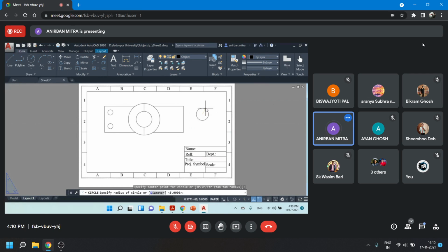If I draw a circle, okay? I have gone out of the command. Okay, circle has been drawn. So it's simply hitting enter that will bring up the previous command again. Okay, sir. Specify center. So that is just a keyboard shortcut. I think I should have mentioned this before, but somehow it skipped my mind. So it's a very useful option to have. If you want to repeat the previous command, simply hit enter.